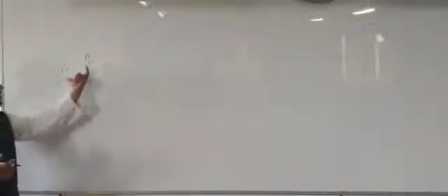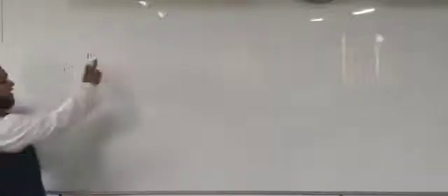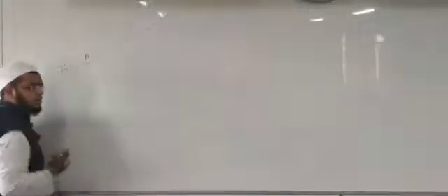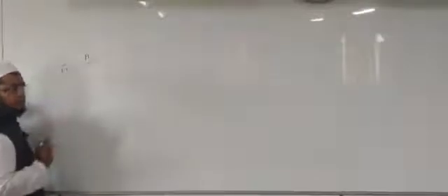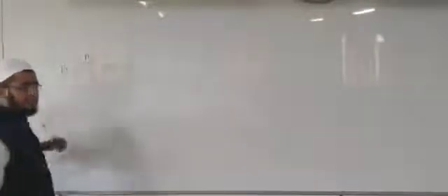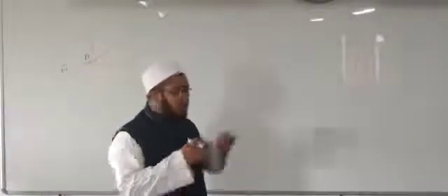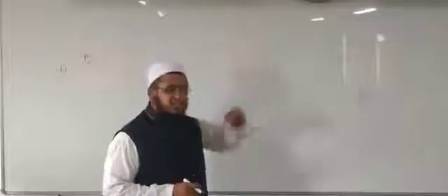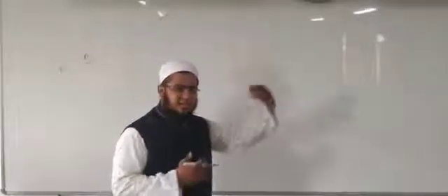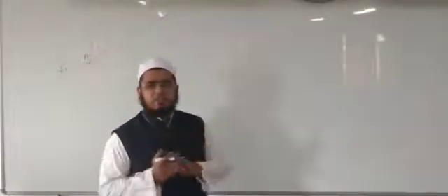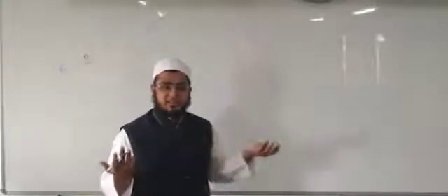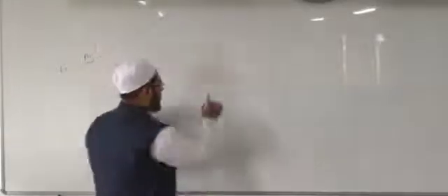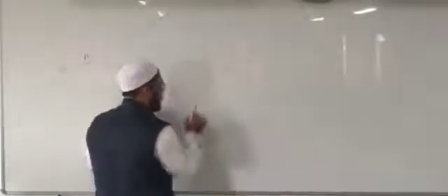The law of transmissibility of force states that this force F1 can be shown anywhere along the line of action. The effect does not change. The best example is when we go to a mall or an office. On the glass door, "pull" or "push" is written. If one side is a pull, then the other side is a push. The effect is the same.